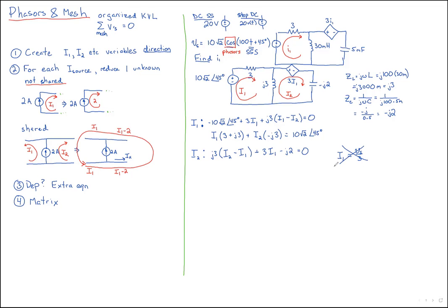But that's not right, because just because there's this voltage between these 2 points doesn't mean there's that voltage across the resistor. Just because you know what the voltage is between points A and B, between bottom and top here, doesn't mean that you know the voltage across this resistor. In fact, the voltage across this resistor will be different than this as long as there's any voltage at all dropped along J3.